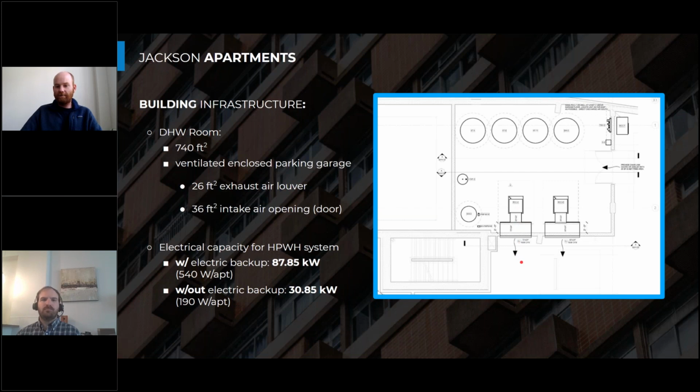That's probably the most cost-effective way to utilize the fans and equipment available with these commercial heat pump water heating systems. But to do that, we want our air flow rate on the makeup air side to be pretty slow. We want the air moving slowly here because these fans don't have that much external static pressure that they can push against. And so that's why we're typically sizing that opening for a slower velocity that the air moves.